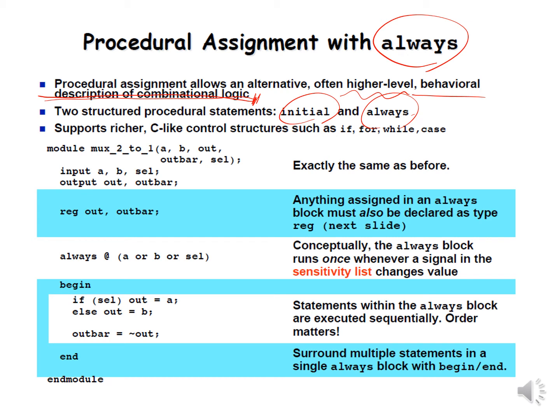The initial statement cannot be implemented in hardware because the behavior of the initialization cannot be done just by using that initial statement. It must be some hardware-driven reset that should be used for initializing the variables.